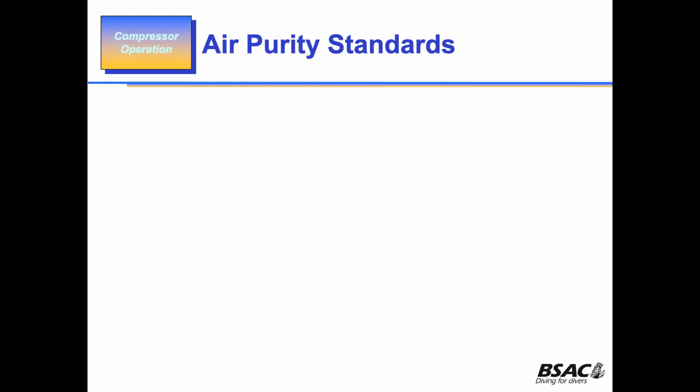We did ours every month. But some say maybe 3 months, 4 months, right? But you have to fill it in and you have to do an air purity test on your compressor, which means you're going to fill a cylinder up and then test the air in that cylinder. You're not actually going to test it on the compressor. You're going to fill a cylinder and then carry the test out on that cylinder.